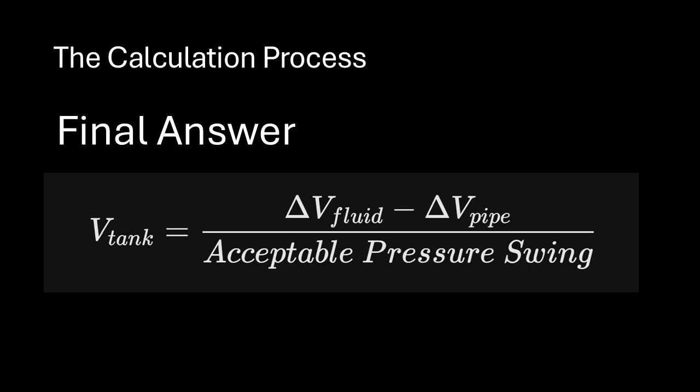By using the long-term apparent modulus in our software, we accurately calculate how much room the HDPE creates for itself over a 90-day season. Every gallon the pipe absorbs is a gallon the expansion tank doesn't have to. This subtraction is the key to preventing oversized, over-budget mechanical rooms.